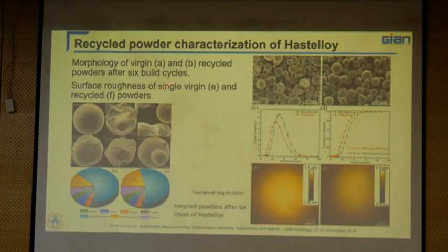If you use these kinds of powder particles, or some kind of recycled powder particles, what is the volume fraction? If you see the powder size and the distribution, recycled and original powder, the red one is original and the black one is recycled, which means the size distribution has changed. Why has the size distribution changed? Because it may be agglomerated, contaminated with satellites, fractured or deformed. Because of all these things, your recycled powder particles change the size distribution.